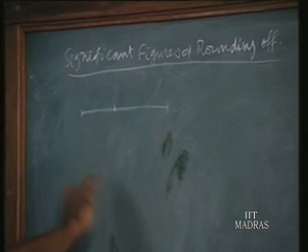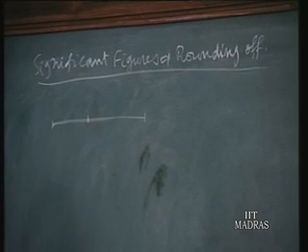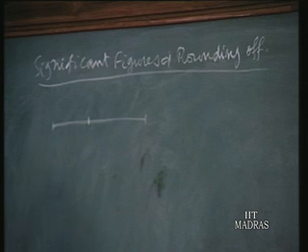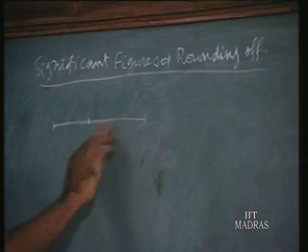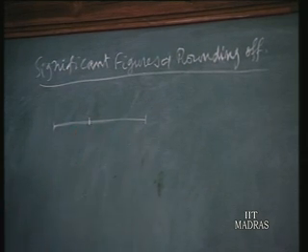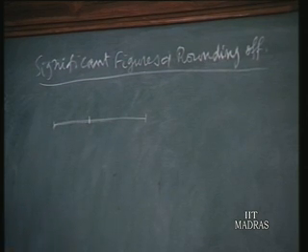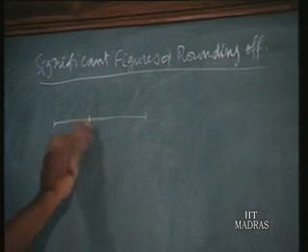Then you cannot simply add those two numbers, because the rough instrument has eaten away the accuracy of the good instrument. So the final measurement will be accurate only to the accuracy of the rough instrument. That is the basis for this.